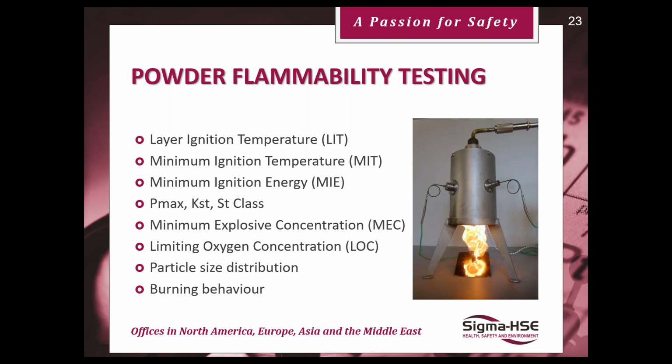So there's various changes. Now, when we're dealing with liquids and gases, it's easy to go to the technical literature. You don't necessarily need to test for flash point or ignition temperature, for example. Most MSDSs that you'll get from the suppliers of your liquids and other materials are likely to have flash point and auto ignition temperature. If they don't, you can search in the literature.